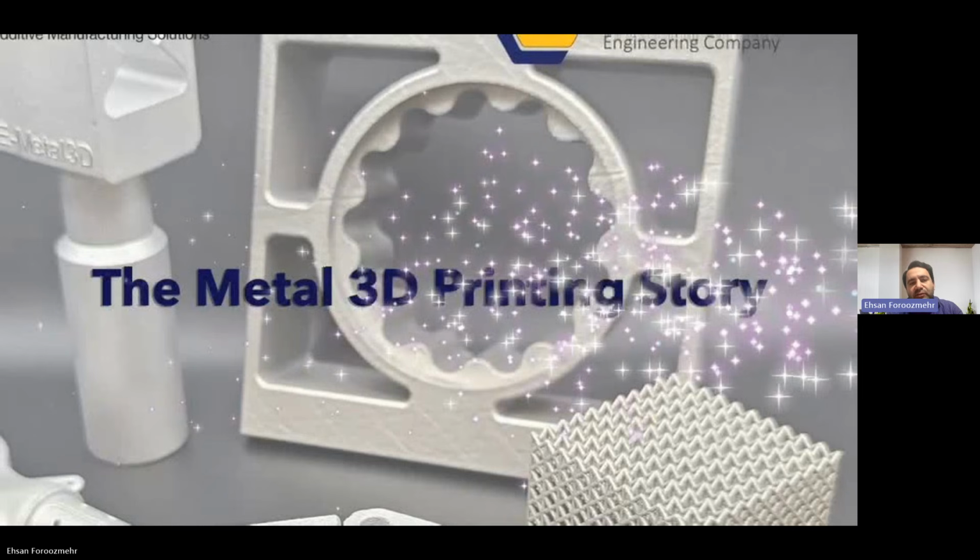If the geometry is quite complicated and you want to make sure about the forms and other aspects of the geometry, then you probably need to use a 3D scanner. That is what is being shown here. In this section, you can apply the inspection software and import the original CAD file with the final 3D scanned part, and you can match them, find the sections that are showing some errors, and realize whether that is acceptable or not. That is a relatively full process of printing and inspection of the parts. So that's the color map showing where there are some deviations, which is where we are going to do some post machining and make that part finalized. So I'm going to stop this here and go to the next slide to use our time better.